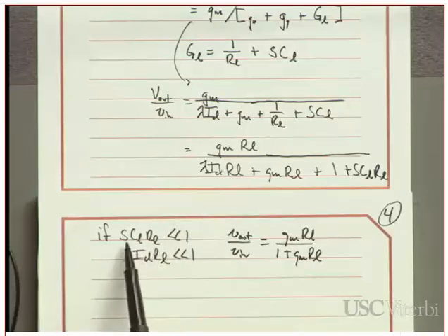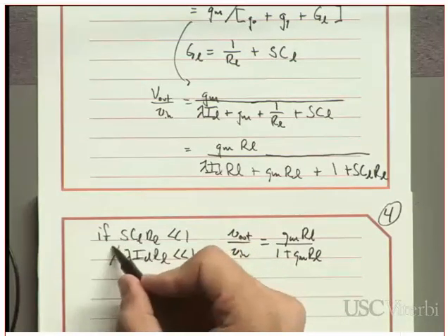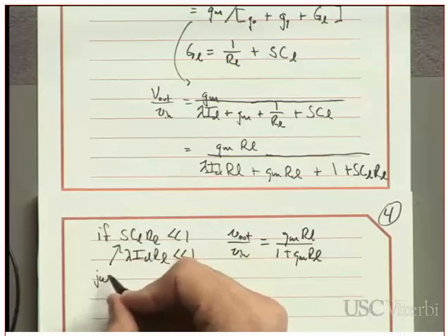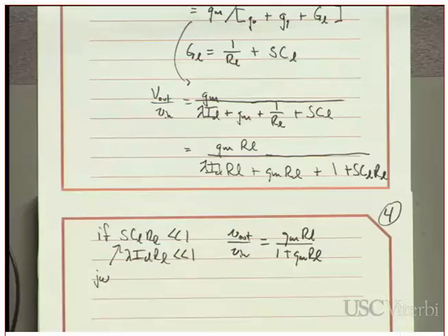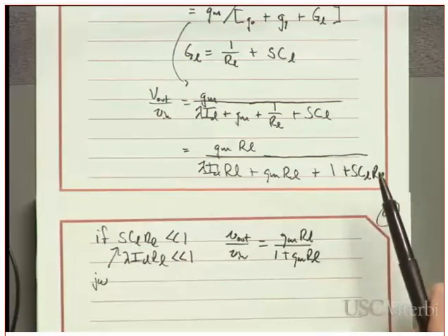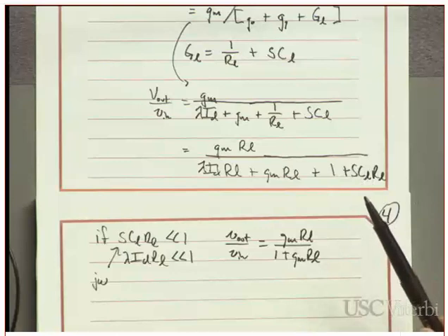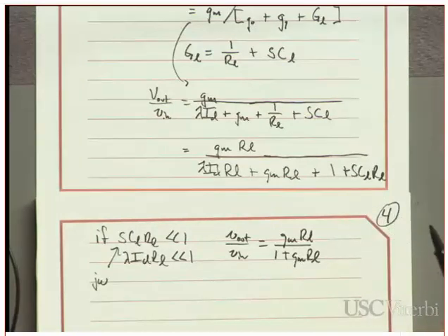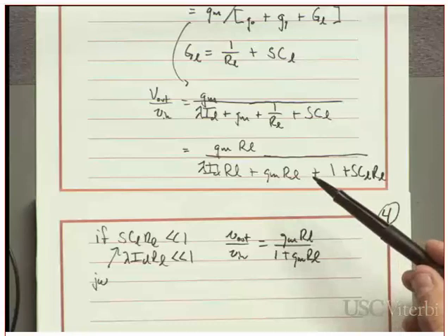And so if my frequency is low enough, that CL times RL times j omega makes this entire term much, much less than 1, then I can assume that next to this 1, this sCL is insignificant. It doesn't have to be anything special; if it's 1/100th, then it's probably small enough to ignore for most cases, right? And the same thing for this one.